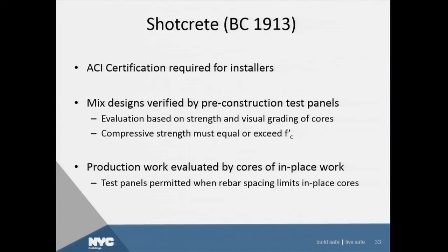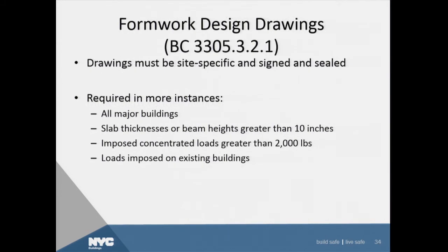There are new requirements for Shotcrete, including that certified Shotcrete installers be used when Shotcrete is used for concrete installation. The formwork design requirements in Chapter 33 have been expanded here. Formwork design is the instances where formwork design drawings are going to be required to be provided by the contractor. Signed and sealed drawings provided by the contractor, or someone working for the contractor, have been expanded in Chapter 33 to basically encompass many more instances than what was previously required.